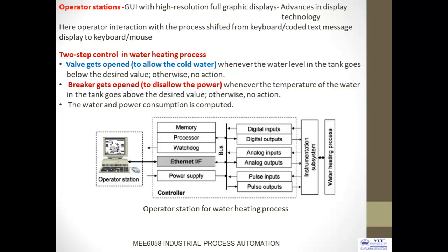Yes, it's possible. If you go into a regular water heater process in our domestic appliances, say we have purchased a 20 liter unit. Once the water reaches around 18 liters, automatically the water valve will be closed and water will not come into the tank. Simultaneously, if you switch on the heater, the water goes to the heater up to a certain temperature. Once the temperature is reached, automatically the circuit breaker will be stopped.